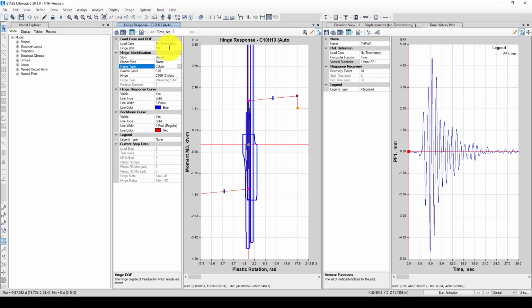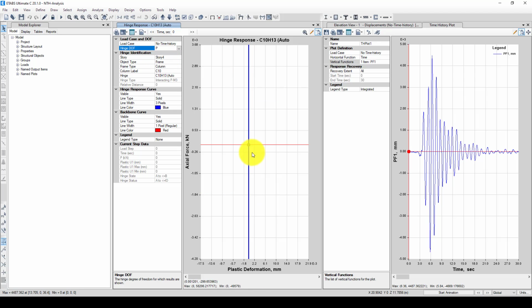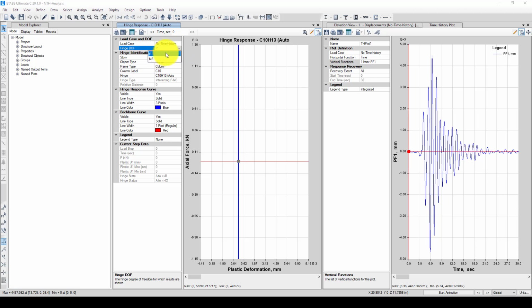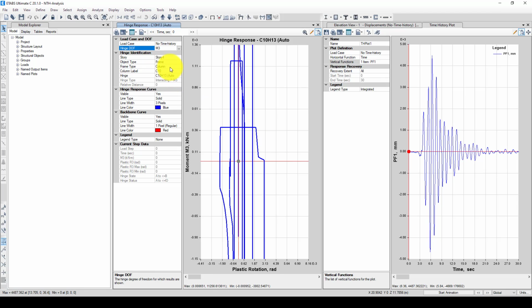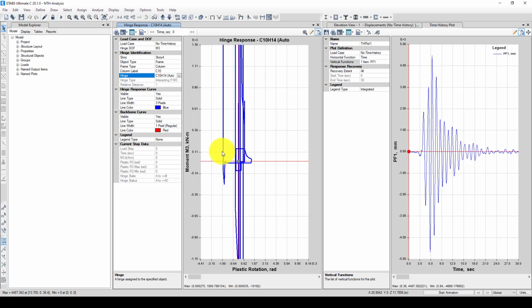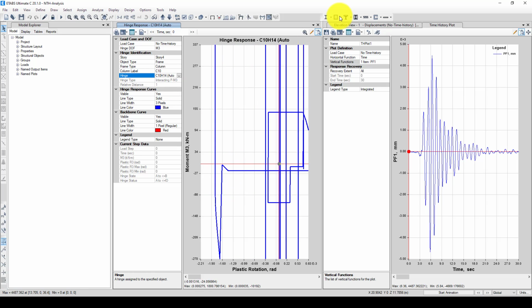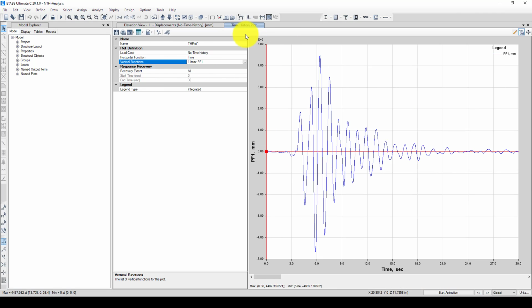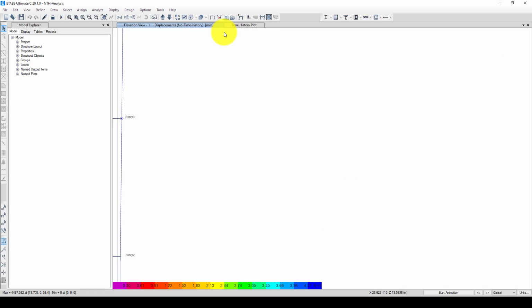If I go back to the hinge here, the column is quite stiff and it doesn't show any deformation in the axial portion, but the moment is like this. If I go to story, let's go to hinges, and show more stories. Yes, it's column 10, and we can go to columns and this one, and you can see the deformation. So like this, you can conduct the nonlinear analysis, as well as use fiber elements instead of nonlinear rotational hinges.